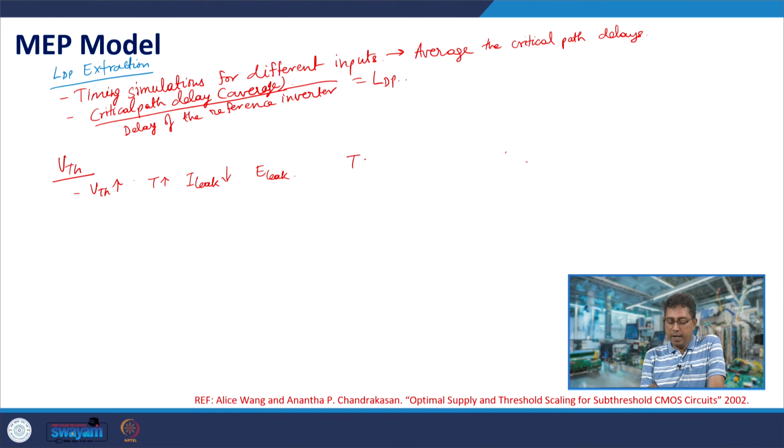So, the total time period, in the previous lectures, we had taken it to be the delay of an inverter into logic depth. So, this is Cg, the gate capacitance, the input capacitance of an inverter or FO4 load. So, it is proportional to the capacitance of the inverter times VDD. Now we are dealing with the optimum value of VDD.